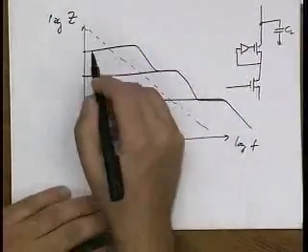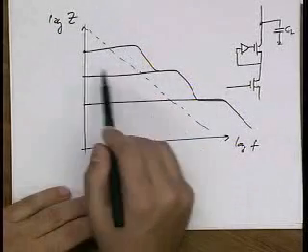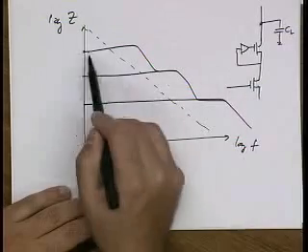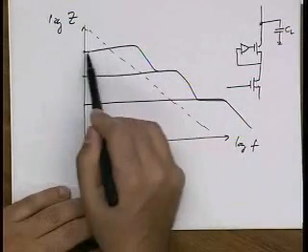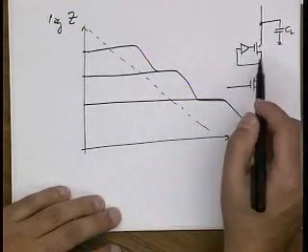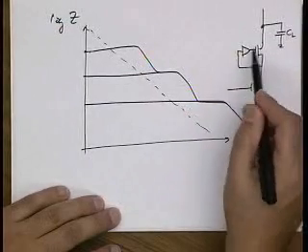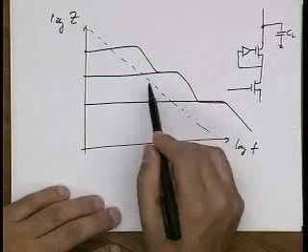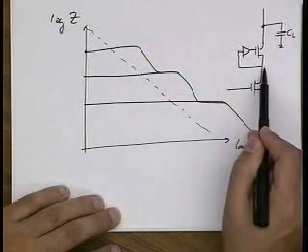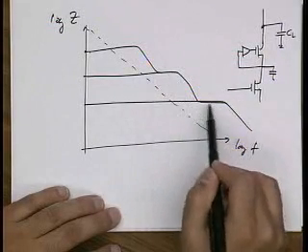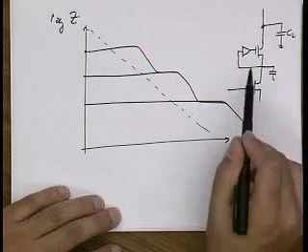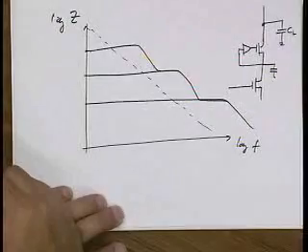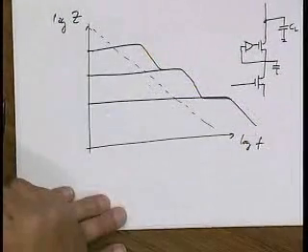So this is actually the impedance that you see out here, real part at low frequency, and it goes out until we hit the 3 dB frequency of this loop, then it drops, then it looks like a regular cascode, then we hit this pole frequency, and it drops, and finally it just looks like a single transistor, because at really high frequencies, even the cascode isn't really helping out anymore. Its gain has gone away.